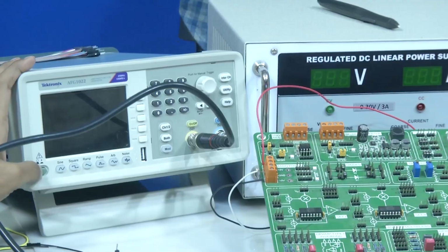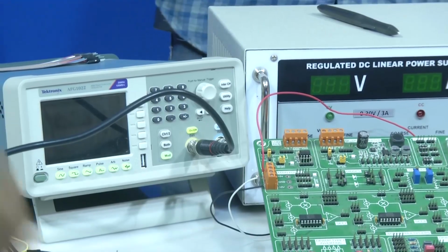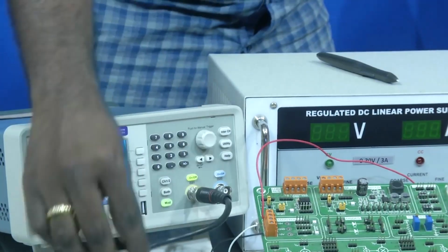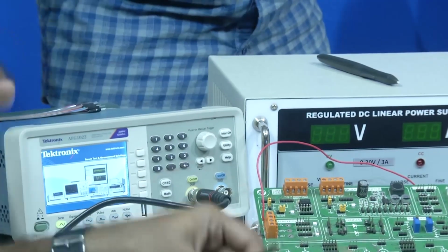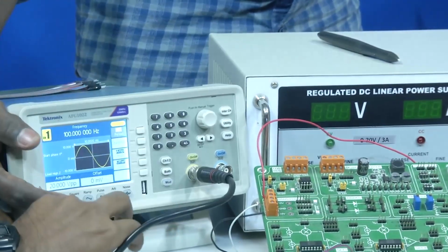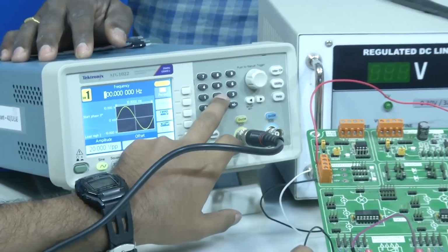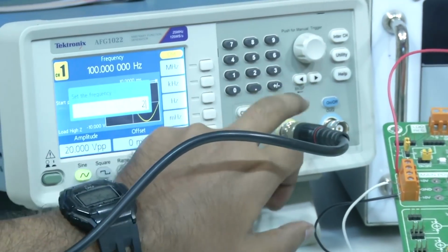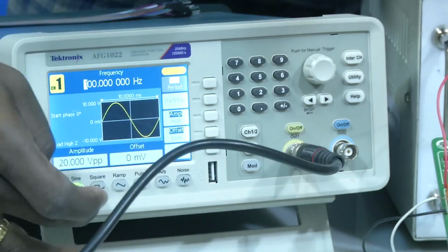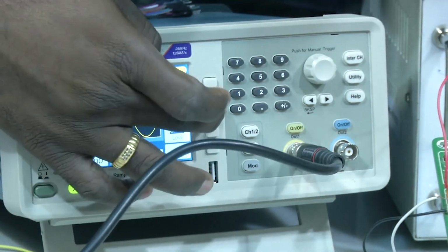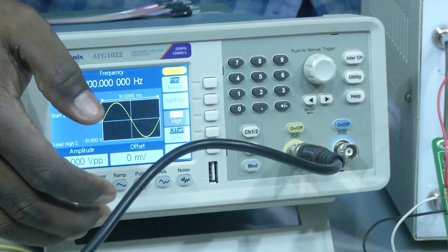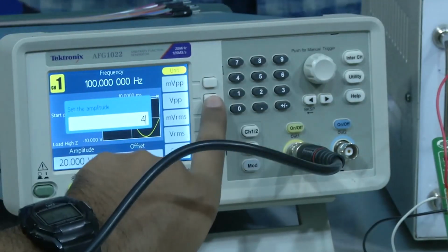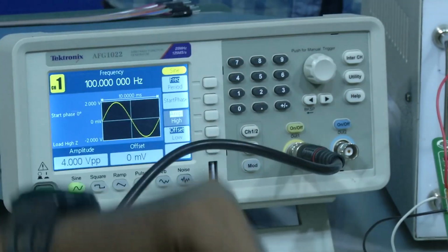Now, we have to put our input signal higher than the positive and the negative threshold values. So, we will set in this function generator the peak value to be more than 1.35. So, we will take 2 volts. In the simulation we have taken a peak to peak of 4 volts, so our peak value is 2 volts. A frequency of 100 Hz we will take. So, we will go to amplitude, and the peak to peak value, how much do we set? 4. So, we will set the value as 4 peak to peak, right. So, the input voltage is greater than our threshold values.